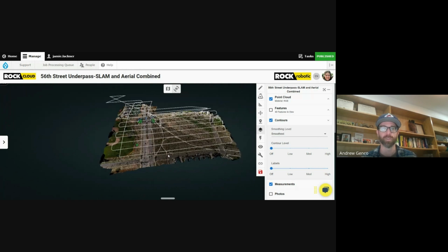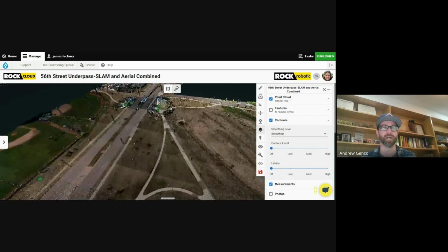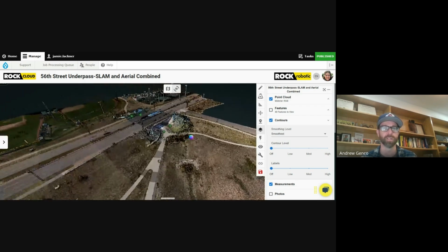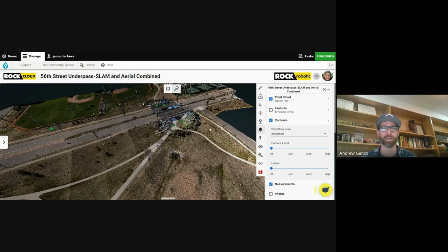When your final deliverables are going to likely be delivered through combining airborne LiDAR and SLAM data, we're using that SLAM in the GNSS denied environments, or where traditional airborne methods aren't going to work. And for the site that we're looking at, this is approximately 40 acres.